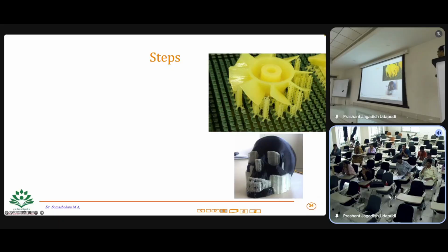if you see these two examples, right? If I want to build this, I need to have the support structure. Again, how you build this support structure is also important, whether it is a fully solid support structure, or you want to have some kind of bridges. When you print bridges, you can save a lot of material. But when you print a fully solid structure and then try to remove it, it will be difficult. But in this case, it is easy to remove.